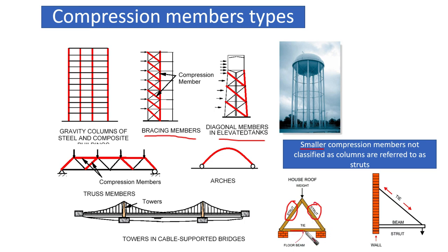And the horizontal one is going to be a tie, which is the floor beam. This is a tensile or tension member. These are compression members. Similarly here, if we have a canopy, for example, this is the beam here. This is commonly a strut. It is going to receive compression force. However, this is the tie that is going to receive the tension force. Okay.